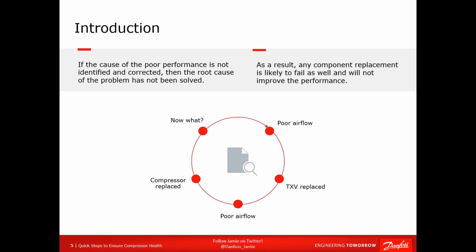The reason I say airflow is because over 50% of the systems that are out there have such poor airflow that it negatively affects system performance, to the point where it reduces the life of components such as the compressor. So it's very prevalent.